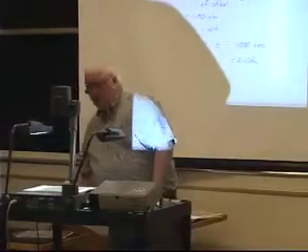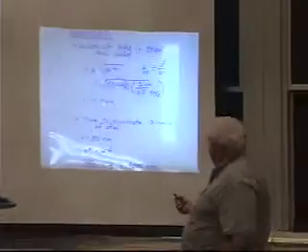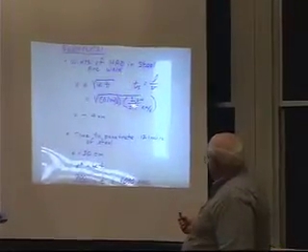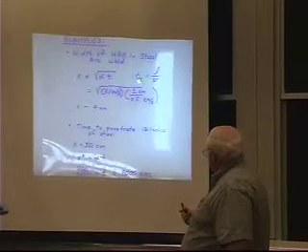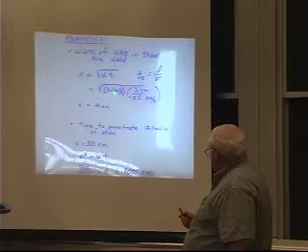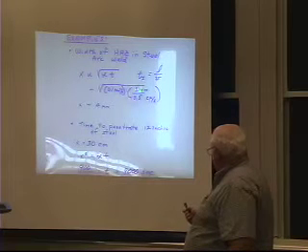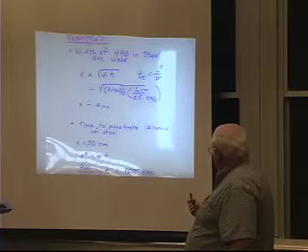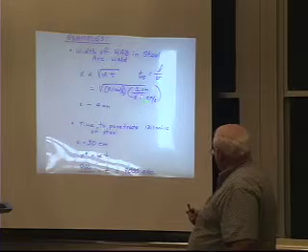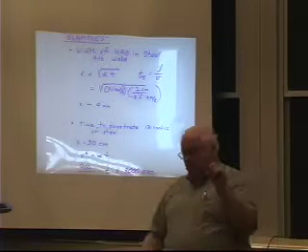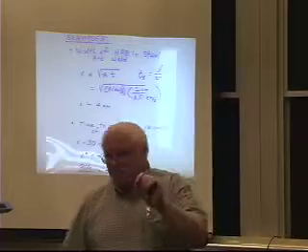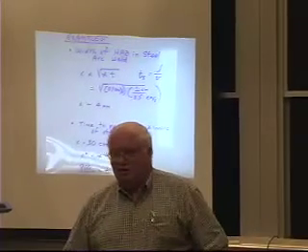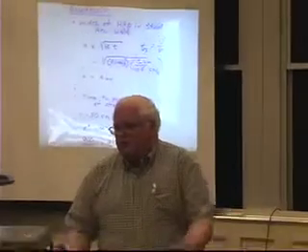But anyway, this is the one where we estimated the width of the heat affected zone in a steel arc weld, and we said, I guess we had 0.5 centimeters squared per second, here's the thermal diffusivity of steel, here's the length of the weld pool, the interaction time is the length divided by the travel velocity, and you end up with 4 millimeters. And if you look at an actual weld specimen that's been etched, it's about 1/8 of an inch or a little larger. So approximately, that's the number.